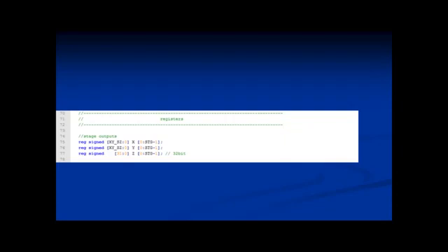Next are the x, y, and z register declarations for all stages or iterations. In this case, each x sub i and y sub i will be 17 bits wide, and z sub i will be 32 bits wide. Notice that there is a set of registers for each stage instead of just a single set that gets reused for 16 iterations. This is known as pipelining.